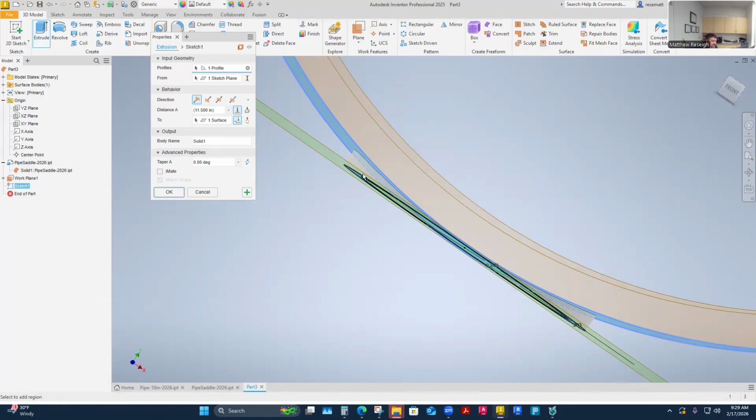You just hit the plus sign, the other way from the same sketch, right? Same profile, yeah. So that's what this is for, to apply a new extrusion from the same sketch, which is the same difference as doing one, then returning to the sketch and using it again to do the other one, and then joining those solids. So you can do that within here and do two different directions.